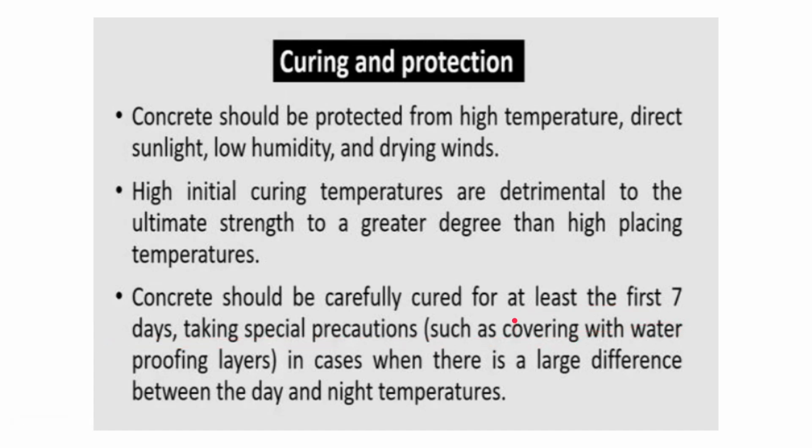To be guaranteed that the minimum strength is developed, it should be carefully cured for at least 7 days, taking special precautions such as water covering, like a waterproofing layer cover, especially in the case of higher temperature difference. That may also be an ill effect because of the freezing and thawing.